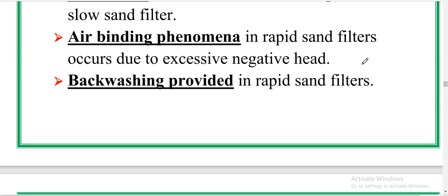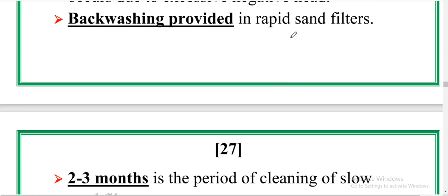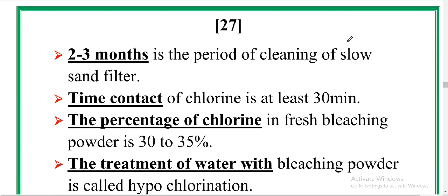Air binding phenomena in rapid sand filters occurs due to excessive negative heads. Backwashing is provided in rapid sand filters. 2 to 3 months is the period of cleaning of slow sand filters.